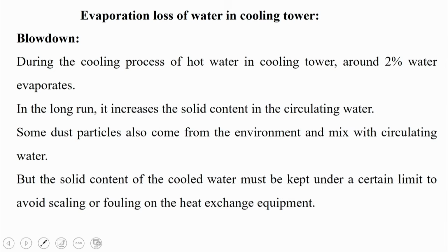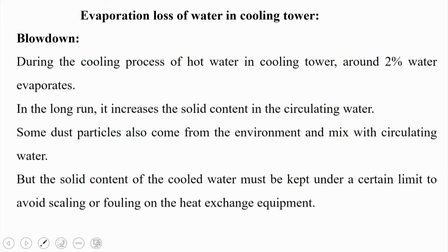In the louvers, on the different sides of the cooling tower, and also at the bottom, a huge amount of algal growth takes place, and some amount of suspended solids are also deposited there. So, in the long run it increases the solid content in the circulating water. Some dust particles also come from the environment and mix with the circulating water, but the solid content of the cooled water must be kept under a certain limit to avoid scaling or fouling on the heat exchanger or equipment, or anywhere this cold water will be used.